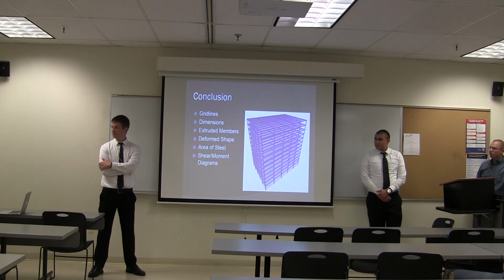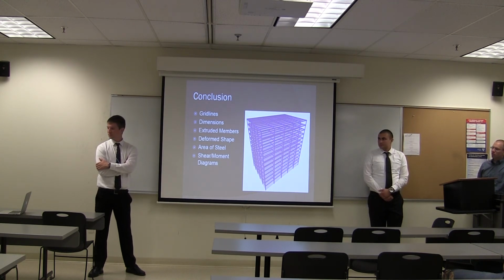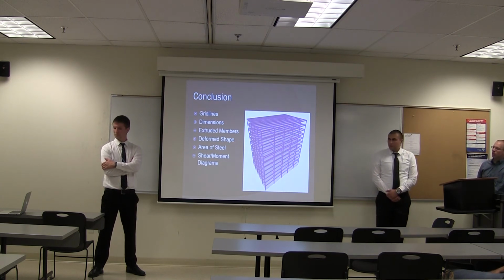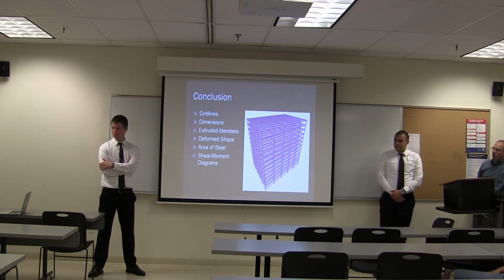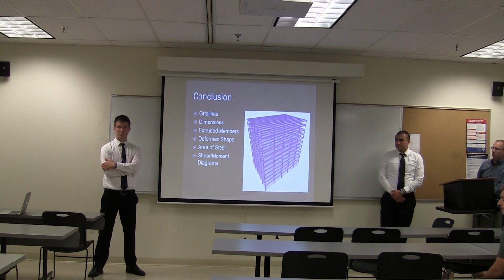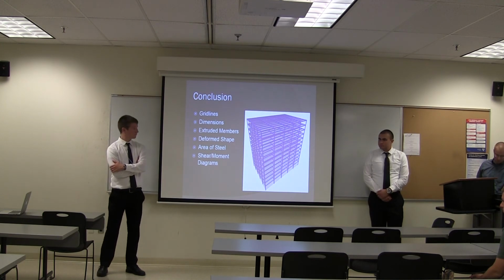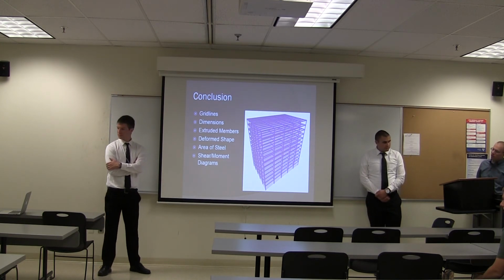So either you do what Ryan is saying, but that will give you only flexural design, and the shear design is done by hand, manually, and you show that in your detailing. Or if you want the software to verify or do the shear design for you, you have to go with the column for the cross section. And again, everything can be like a beam-column, it depends on the reinforcement. Now, again, guys, every time you do this in any presentation, this is not a conclusion actually.